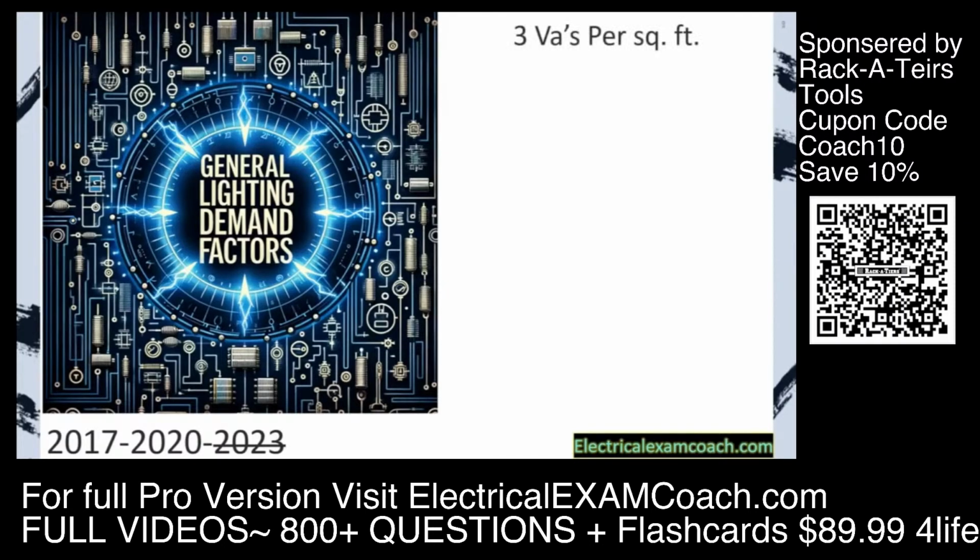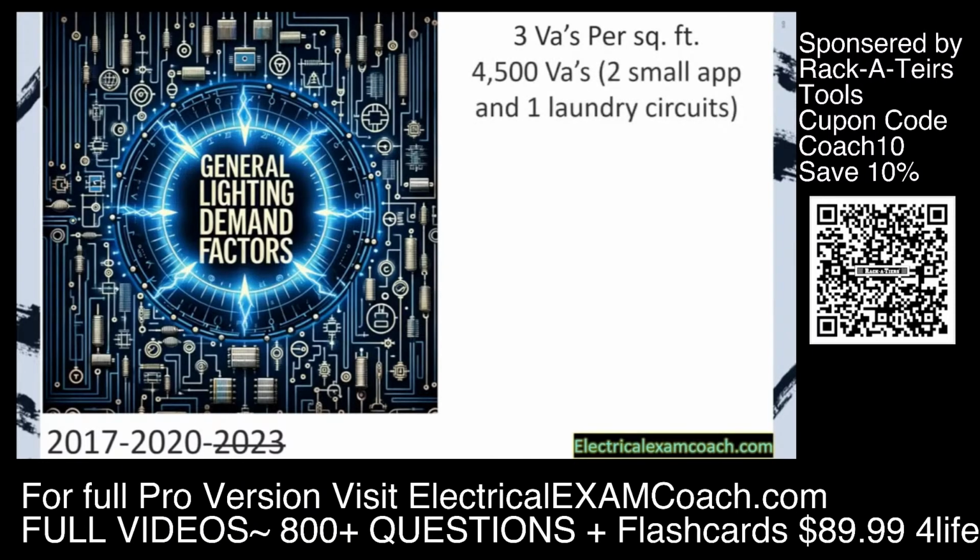Now we're going to learn how to apply the demand factor to the general lighting load. At the beginning of the program, we learned that it was 3 VAs per square foot, and we had to add on the 4,500 VAs for our 2 small appliance and 1 laundry circuit.